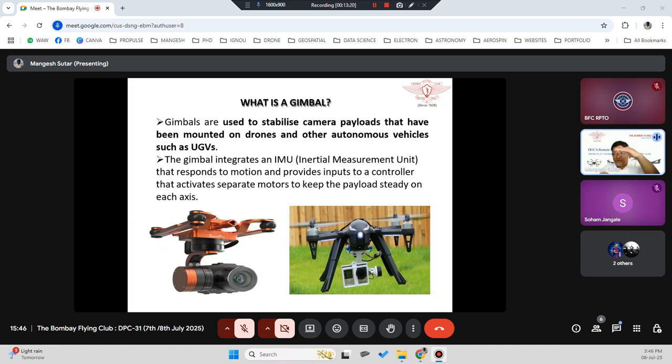Second, if you want to adjust your drone, you are consuming the power of the drone battery. But if your drone is simply stable, hovering, you are at a very optimal battery utilization, and you are only using minimal power for controlling your gimbal. The gimbal has very small motors which only control two motions, right? Pan and tilt motions. So it will not consume much power compared to the power consumed by the propeller motors. Okay, so that's why you are always advised to use a gimbal with your camera to stabilize your footage.